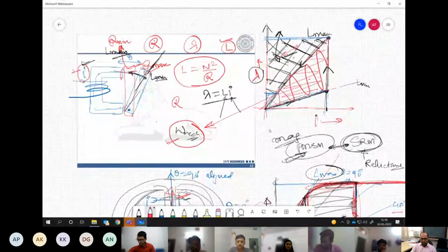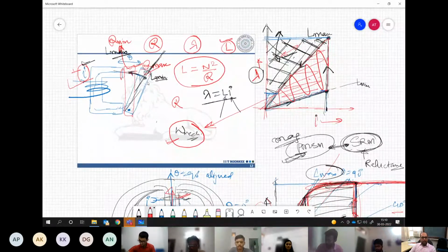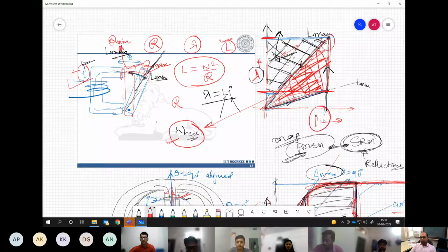electromagnet and we are trying to excite this coil and this plunger moves, effectively what is happening from the magnetic point of view. So we are trying to get the work done, and which is basically this area within this triangle, which is the difference between the present flux linkage and the final flux linkage, keeping the current constant. So that's the kind of area we are getting over here. And whatever is remaining, this upper triangle, that is basically transferred back to the source. This is only required for magnetizing the core.